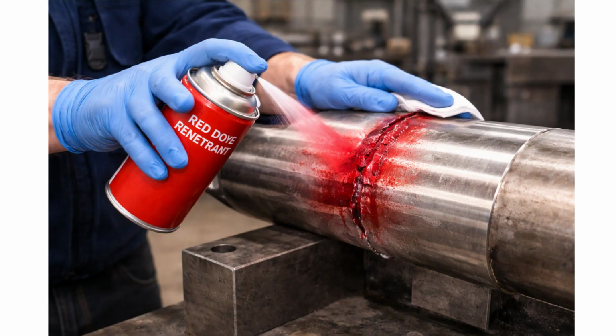Step 2. Penetrant application. Once the surface is properly prepared, it's time to apply the penetrant. The penetrant may be applied to the test component by dipping, spraying, or brushing. For small parts, dipping the entire component into a tank of penetrant is efficient. For large structures like welds on pipelines or aircraft fuselages, spraying from aerosol cans is more practical. And for very localized inspections, brushing works perfectly fine. The key is to ensure complete coverage. Every square inch of the surface you want to inspect must be covered with penetrant. You can't inspect what you don't coat.